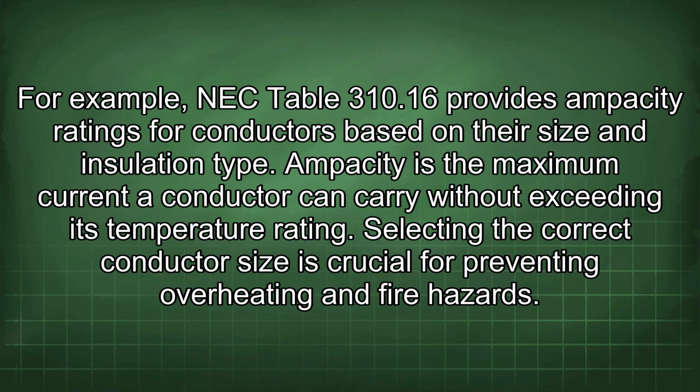For example, NEC Table 310.16 provides ampacity ratings for conductors based on their size and insulation type. Ampacity is the maximum current a conductor can carry without exceeding its temperature rating. Selecting the correct conductor size is crucial for preventing overheating and fire hazards.